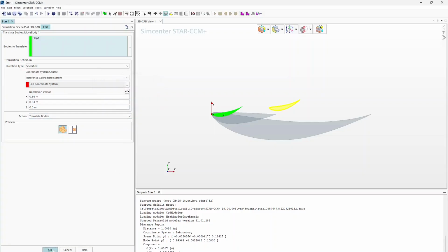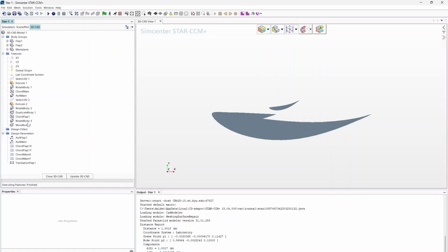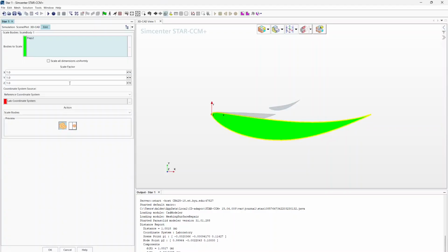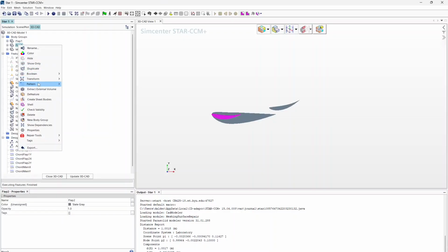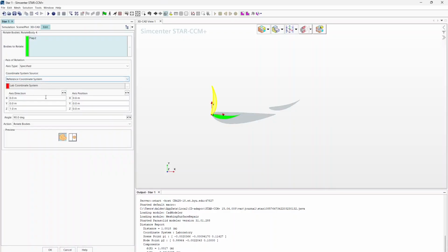Okay. And now we simply just need to do all those same things for the second flap. So we will scale, and this time I'll shoot for 180 millimeters, maybe just a little bit smaller, and expose this parameter. Instead of flap 1, this is flap 2, and again expose, and this is to Y. Okay. Now let's grab this guy and rotate him for our angle of attack.